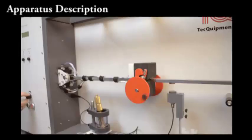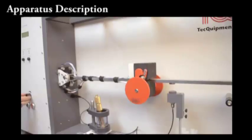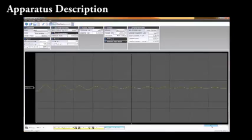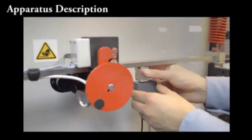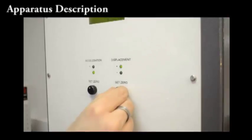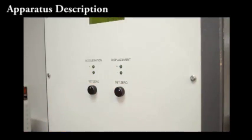The control section has a display showing the speed of the exciter disc when used for forced vibrations. Other controls include the set 0 adjustments for the displacement and acceleration sensors. Make sure that the set 0 lights are off during the different steps of the experiments. There are 2 special metal calibration blocks available with the equipment. Students do not need to use these blocks to calibrate the sensor. However, if necessary, you may need to make some small adjustments to the set 0 controls so the VDAS trace is at the center of the chart.